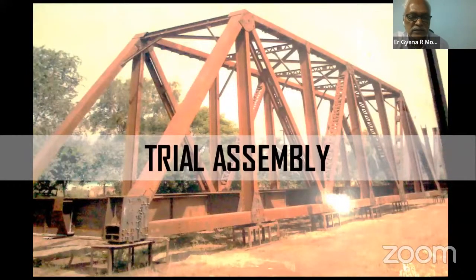Then trial assembly. Once the girders are finished, we come to the trial assembly. Trial assembly is equally critical, equally tricky. The reason being, these girders, as I told you, are pre-staged or shortened component girders. That is vertically shortened, in some places diagonally shortened, so that we have to fit it in such a way that we get the right kind of camber. Because the bottom chord components, if you check the length, are supposed to have a higher arc length than the theoretical length at the time of assembly.